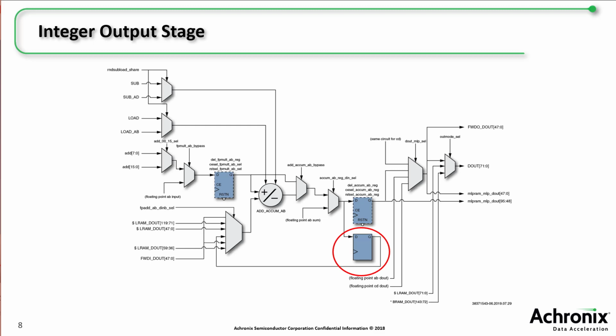The result of the adder accumulator can then be routed to the MLP outputs. Note that as well as the direct output, there are also a number of supplemental outputs which can go direct to the register file as well as cascaded outputs to the MLP above. Finally, remember there are two parallel integer output stages. These can either be combined or output in parallel.